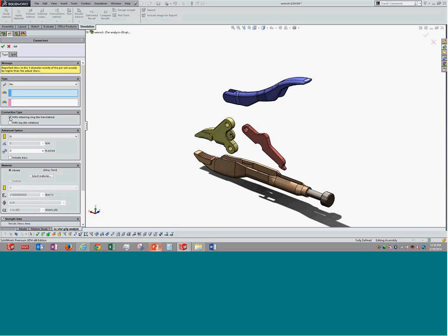Second part of the question, I think I can answer, wherein you are asking how we optimize edge welding by using the edge weld connector. Let me tell you what happens. Whichever location edge welding is done, you create them and solve the analysis. After the analysis is done, you can see the forces that are coming in the edge weld, and you can understand how the forces are varying.